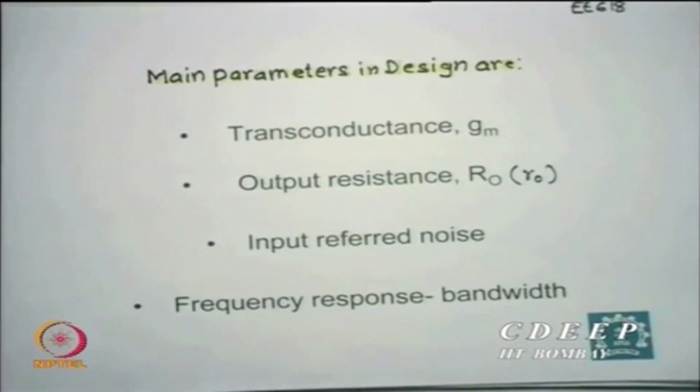How much is the tolerable input referred noise, how many dBms or dBs corresponding to a given signal, essentially it converts into what is more popularly known as signal to noise ratio. How much is this noise at input to noise at output ratio is very crucial for any amplifier. Okay. So this input referred noise is essentially a basic noise available without anything external, and if that is going to change or increase, then your purpose of amplification may not be as good.